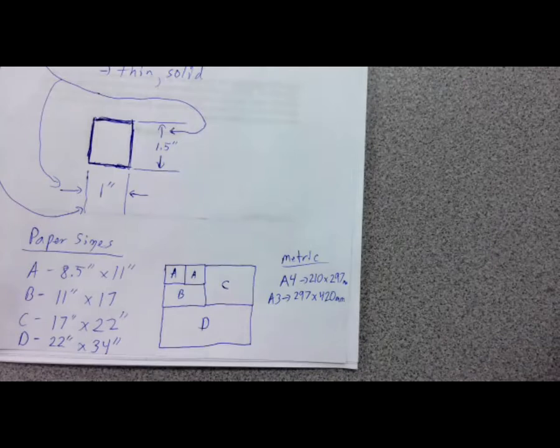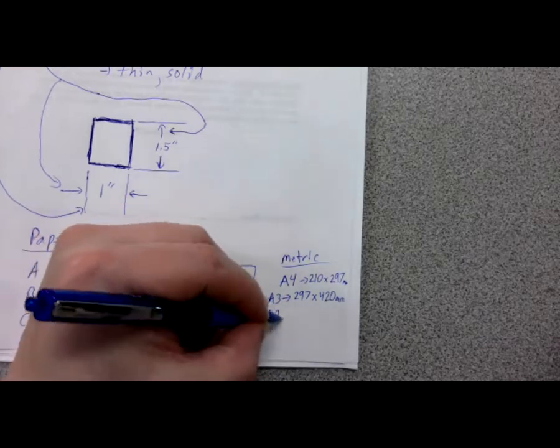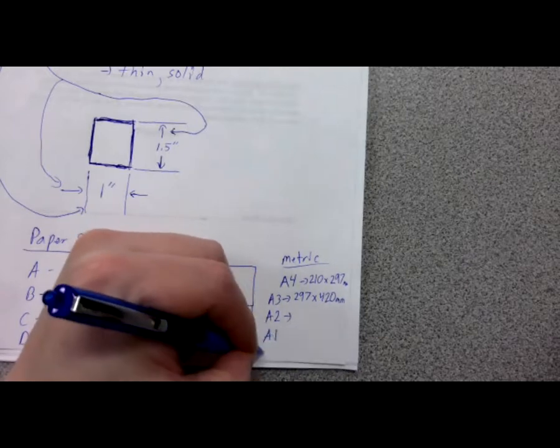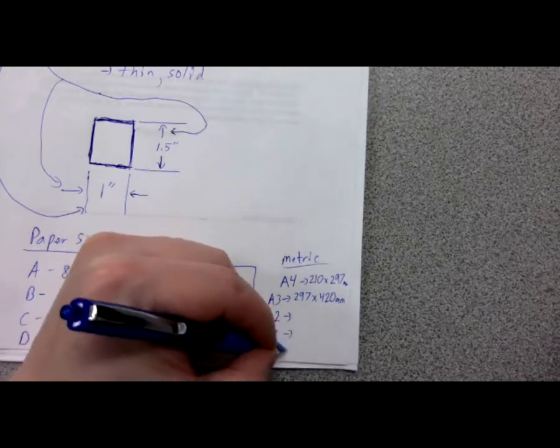Okay. Now, the reason I bring this up is when you go into SolidWorks, and we'll have SolidWorks make drawings for us, one of the first assignments, it'll ask what size paper you want the drawing to be on. The default will probably open up with the metric sizes. So if you see A with a number after it, those are metric sizes. You'll have to dig a little bit to get the US standard, the size A paper. We're not going to write all the numbers out here because you see the pattern, right? You just take the short side and double it.